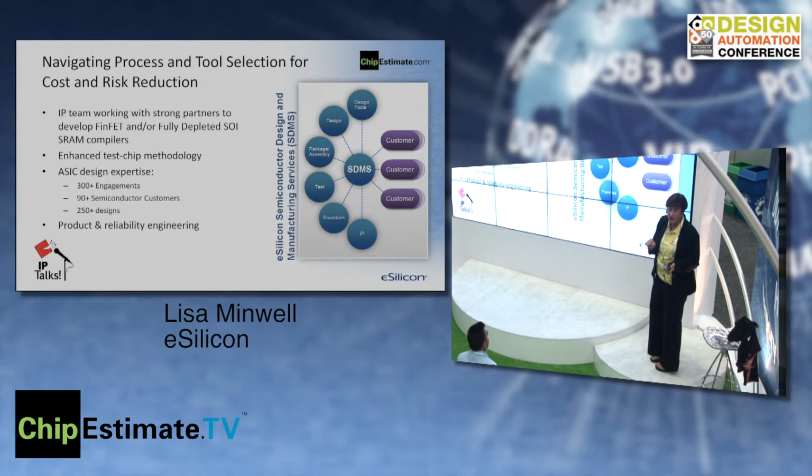But then if there's some spot within that chip where we're not able to meet, maybe it's the performance, maybe the power budget isn't met, etc. We need to be able to go in and selectively remove some functionality that isn't needed, or speed up a path, reduce area. Any of these items, you start with something that is well understood, well studied, well characterized, and characterized in silicon. And then at that point, you take that design and you reduce whatever mechanism it is that you need.